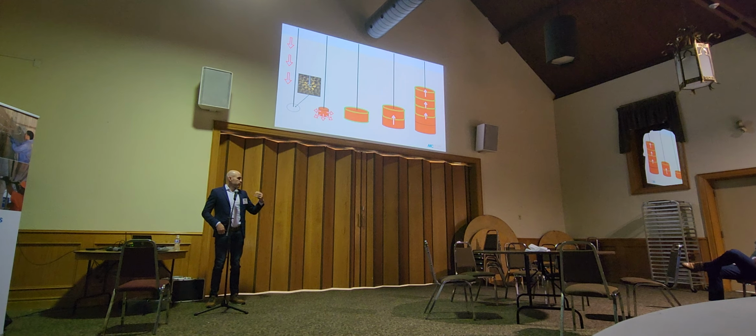After a certain time, after a certain amount of resin, or even after a certain pressure is reached, you don't stop the injection process, you just lift up the remnants, so the pipe, to create pillars in the soil. And this is quite accurate. So if you calculate with 50 centimeters, for example, you can really accurately say, okay, you will need 23.55 liters per meter of this pipe. And then you can just calculate into your steps.